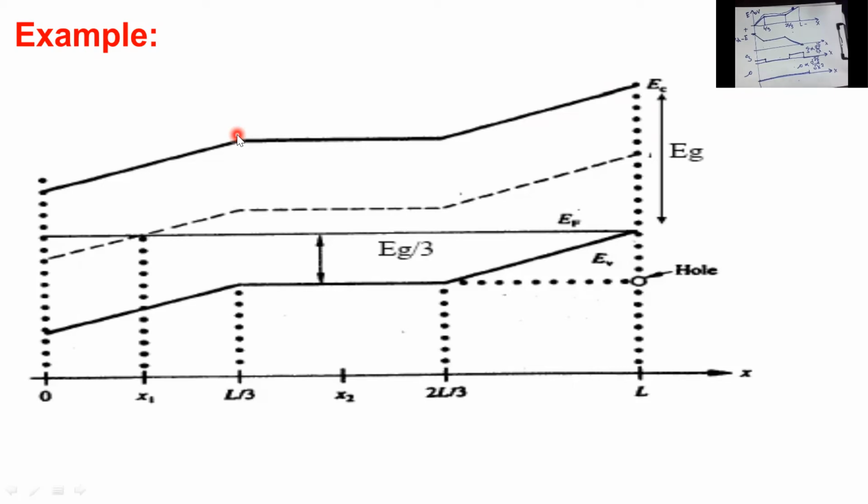Okay, N-type, P-type, intrinsic. To know N-type, P-type and intrinsic, we have to compare the Fermi level with the conduction band and the valence band. Where is the Fermi level? Yeah, this is the Fermi level. This straight line is the Fermi level. Okay, what about this dotted line? This dotted line, without mentioning, is the intrinsic Fermi level. It's E_Fi. Why is it E_Fi? Because it's all the time in between the conduction band and the valence band. So this dotted line represents the intrinsic Fermi level. Let me annotate it. So let me use a pen now.